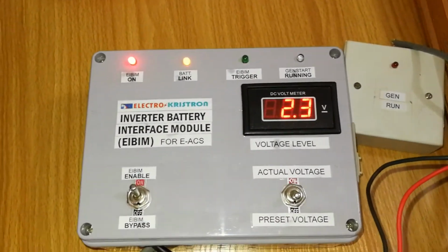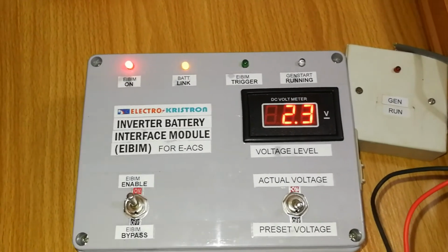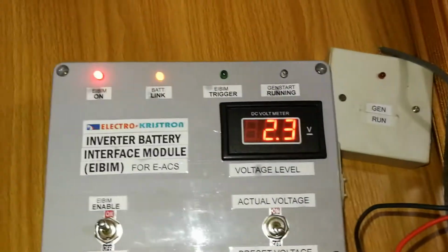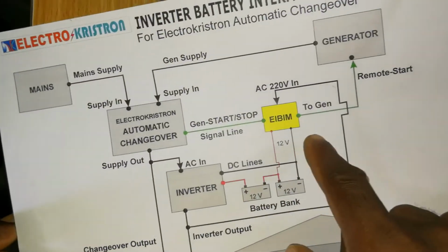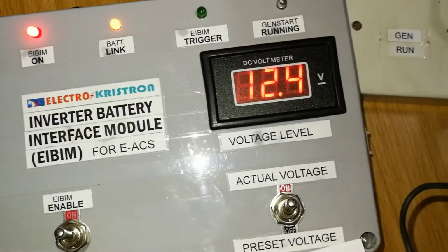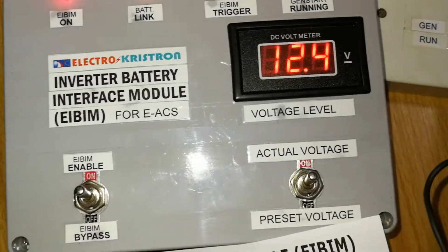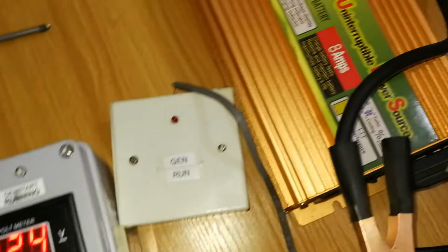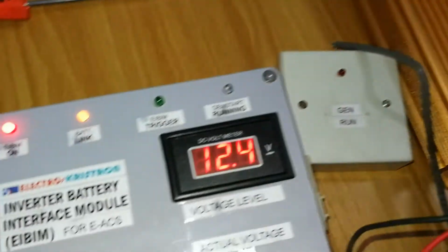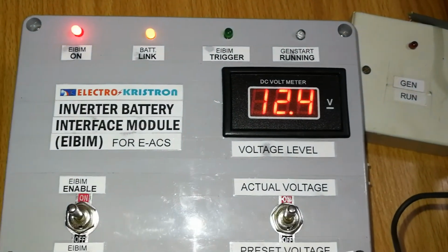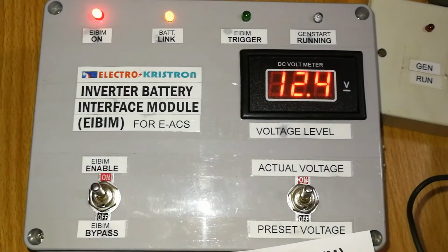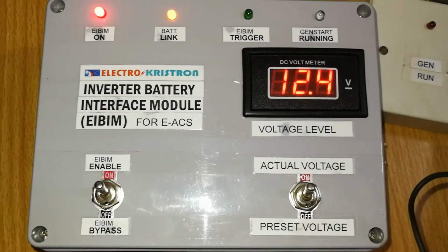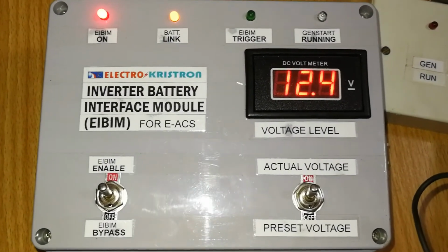As it is coming down during use, the actual voltage is also coming down with it. For most inverters, when that voltage level drops to 10.5, they are no longer ready to keep operating. A lot of them start turning off or maybe buzzing at that level.